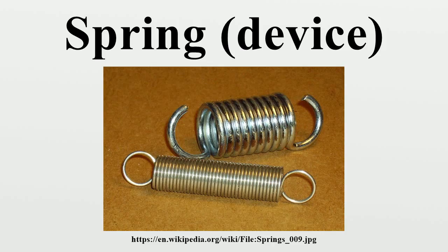The most common types of spring are: cantilever spring, a spring which is fixed only at one end; coil spring or helical spring; and conical spring. These are in turn of two types. Compression springs are designed to become shorter when loaded. Their turns are not touching in the unloaded position, and they need no attachment points. A volute spring is a compression spring in the form of a cone, designed so that under compression the coils are not forced against each other, thus permitting longer travel.